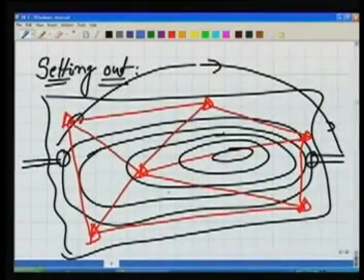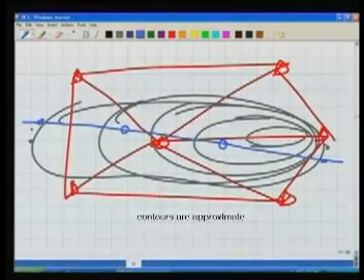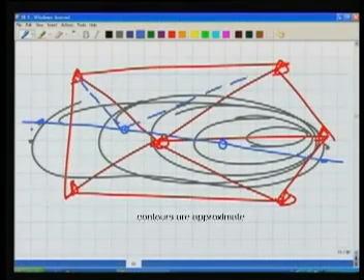Now once in the field, you have to locate where the shaft is, where the center line is, how much deep you should go in the shaft here. So in order to locate this shaft, for example, we will make use of the control network. Let us say just for this case, this shaft makes certain angles from the line here, which is the control line, a line made by the control network.